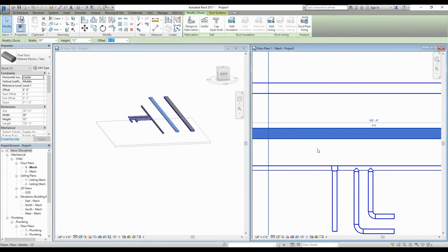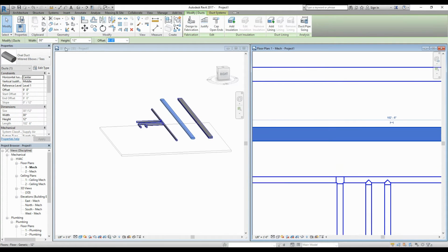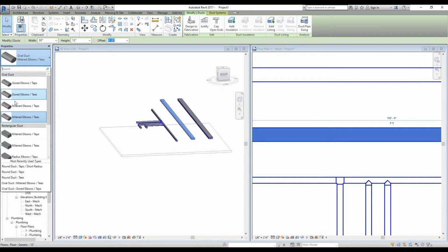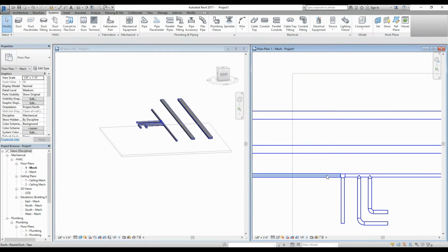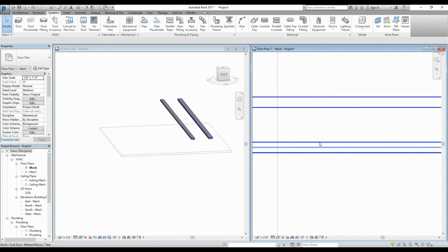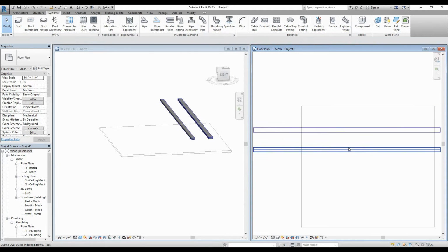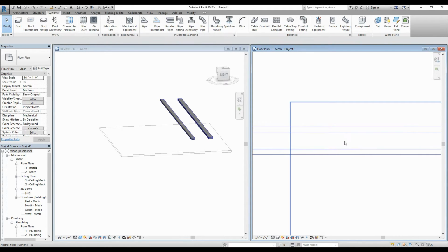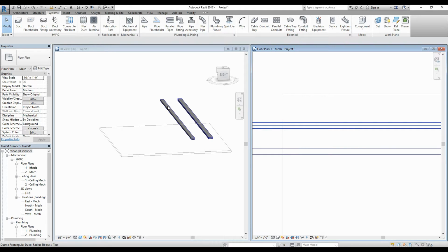Now moving on to the elliptical. You can see the first section indicates the type of elbows, and then the tap or the T's, the branch connection. So I'm just going to delete what we had there. If you press Tab when you're hovering over duct or pipe, it'll select the whole branch or the whole system. I'll go over that a little bit later when we get into doing full systems.